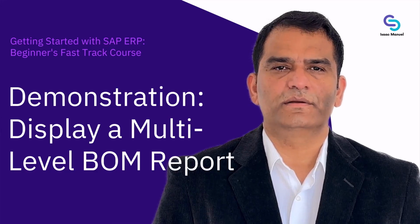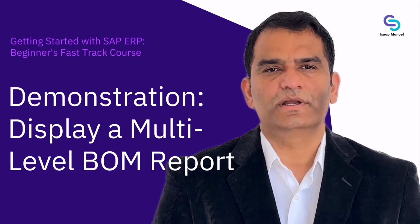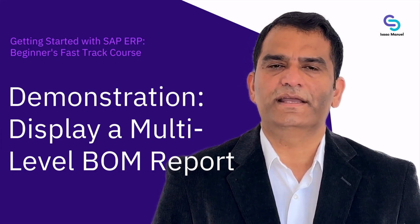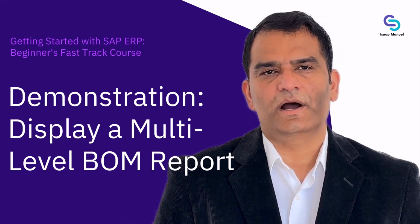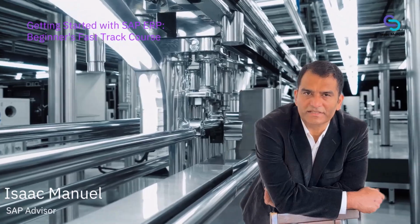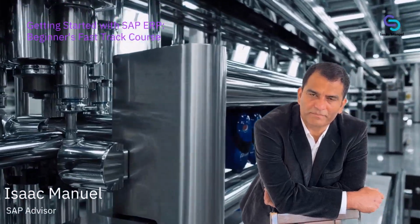Using transaction CS12, you'll navigate to the correct reporting screen, input the necessary material and plant data, and select the appropriate BOM application for production use. You'll also learn how to read the BOM structure, interpret assembly indicators, and analyze how components are layered within a multi-level hierarchy. Let's consider how this plays out at a global manufacturer like Pepsi.